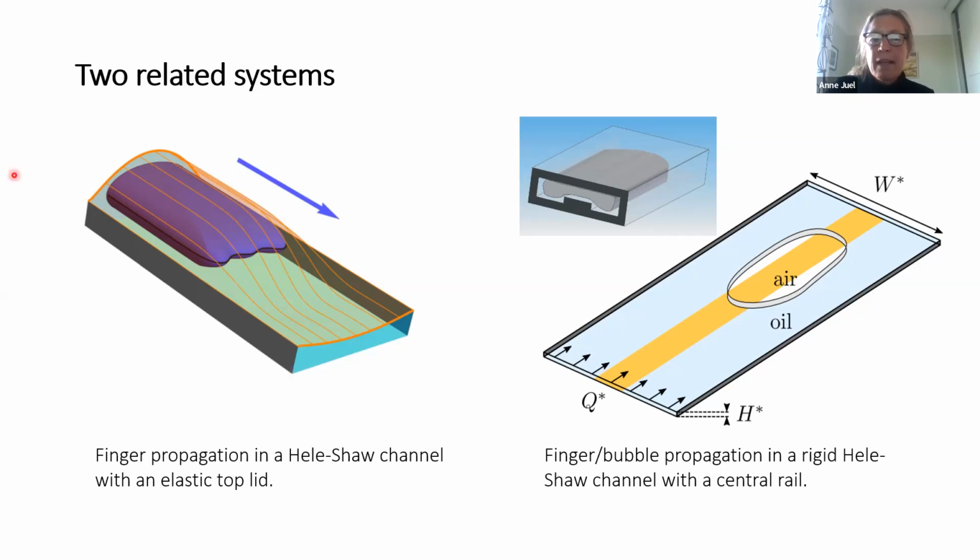The idea is that I want to explore the general landscape of these Hele-Shaw channels, and then explore the propensity for time periodic behavior in these systems. That's why I want to use two related systems, where I've perturbed the geometric confinement compared with a constant depth channel, which is a bit boring because you only ever see a single steady finger propagating in it.